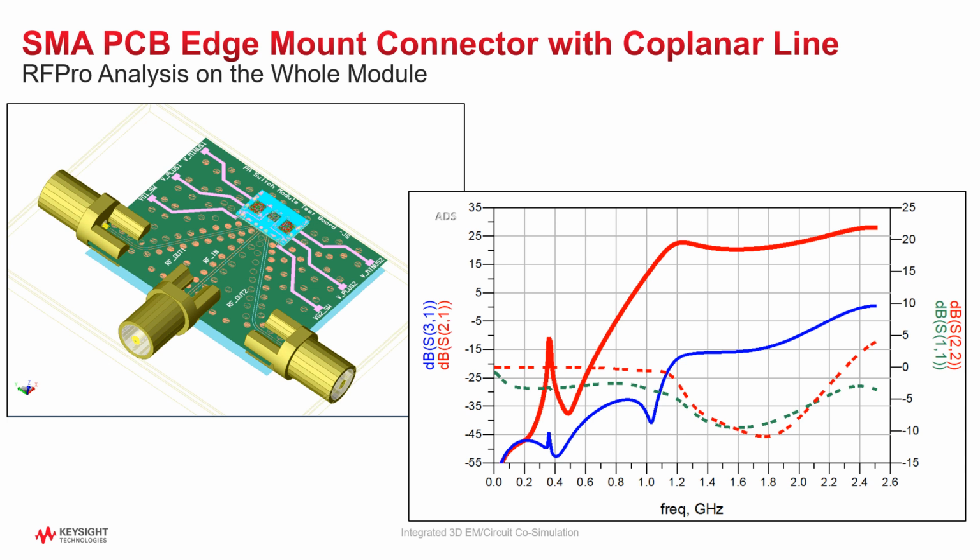Number one, the PA standalone, if you remember, has 27 dB of gain. At the laminate assembly level, we lost 3.5 dB, and we lost another 2.5 dB at the test board assembly level. This 6 dB of loss seems large, and I'm sure a big part of it can be recovered by revisiting critical junctions in the assembly and reducing the mismatch losses. Number two, the low frequency spike we talked about needs to be better understood and fixed. Also, the bias network needs to be improved and have better isolation from the RF section.